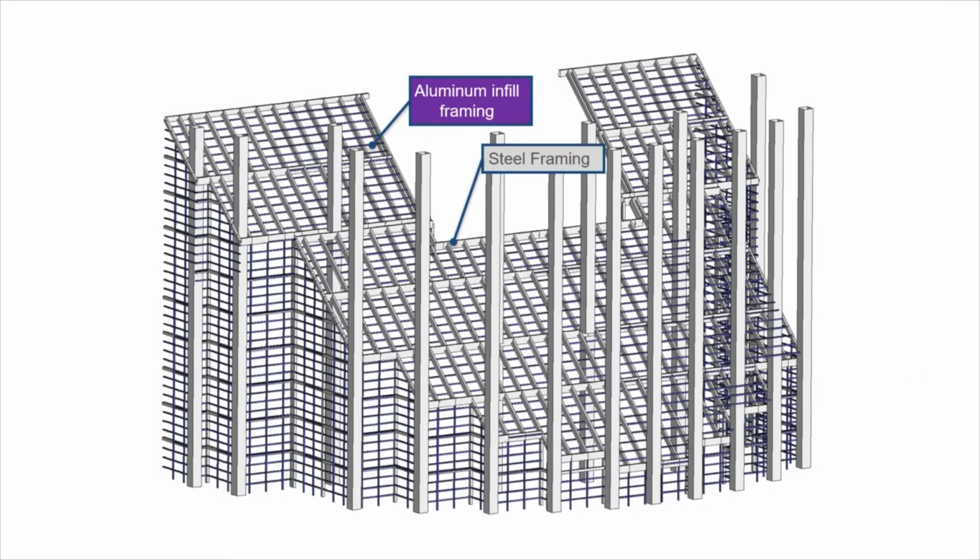Just from a structural model perspective, this kind of shows the density. So you have a primary steel structure and intermediate aluminum framing between that, and so you get this very dense grid and relatively small panels. But that was what was available at the time, and that was as transparent as they could achieve in 1982. We were asked to re-examine this to try to make it as transparent as possible.